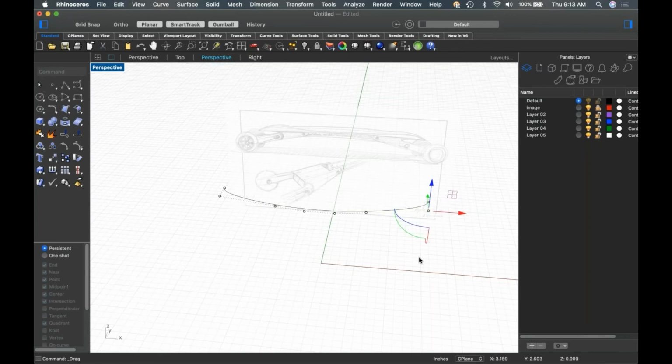I'm going to snap that to that end. And what that does, because these 2 points are in line, that means that they are set up for an axial tangency, right? I can flip across the center line and make a symmetrical object and know that they're going to be symmetrical side to side.